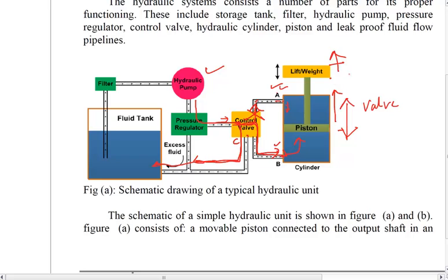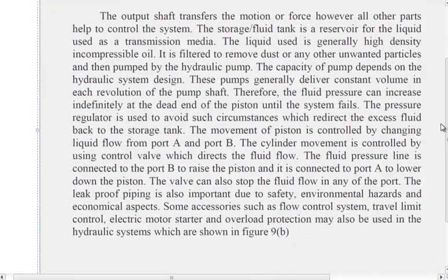The same principle is used even in the JCB arm. You might have seen the JCB has an arm, and that is used to do earthworks. It does so with the help of hydraulic units like this. You can see this is not a very big piston, it's a very small piston. It may have a circular area of only 0.1 square meters. But as I said, the pressure is going to be decided here by the hydraulic pump. The hydraulic pump might be trying to push too much volume, and that will create a lot of pressure here.